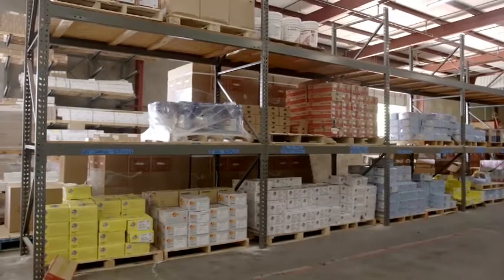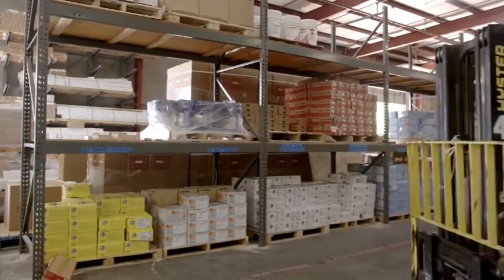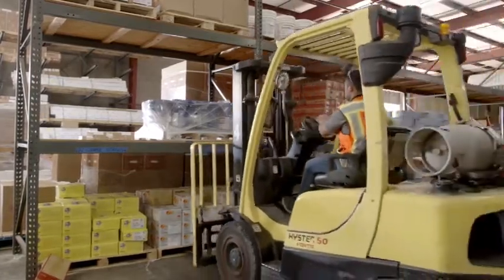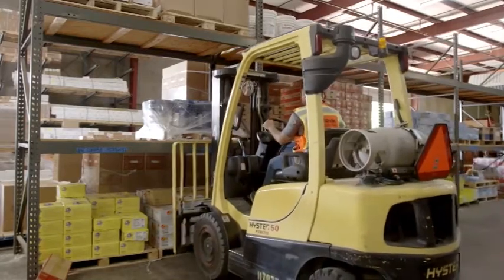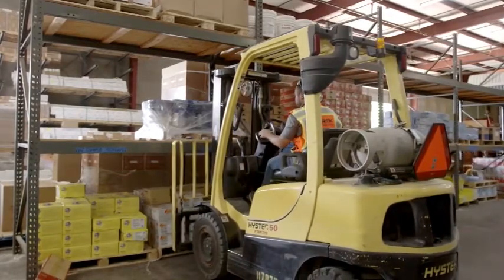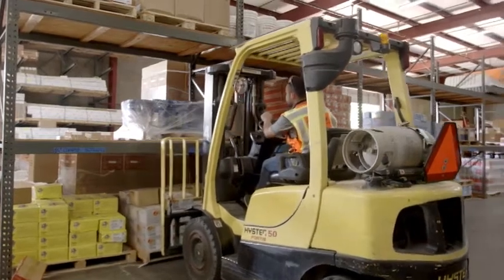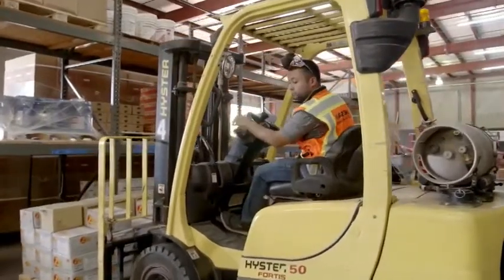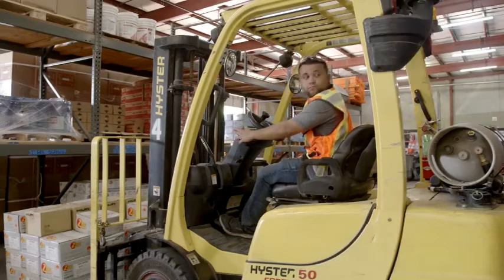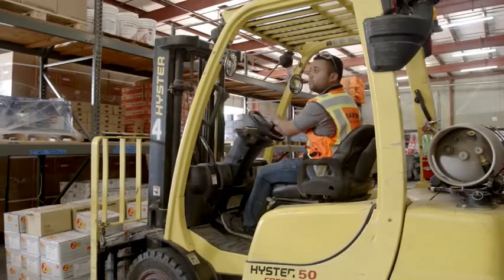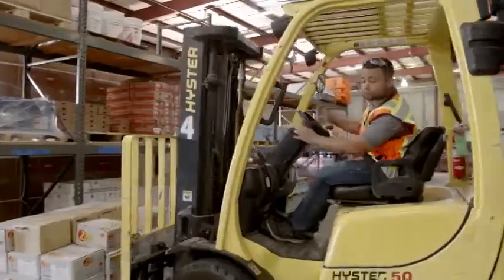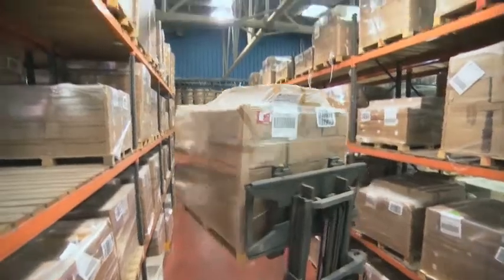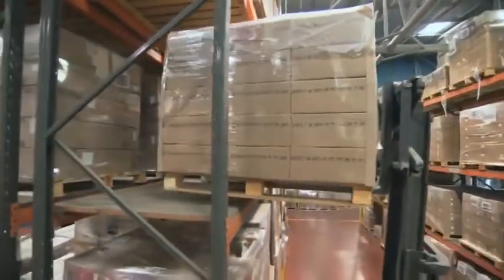Approach the load slowly and carefully, and make sure the truck is squarely in front of the load and the forks are set at the correct height. Forks should be placed under the load as far as possible, at least 2/3 the length of the load, and the mast tilted back carefully to stabilize the load. Carefully lift the load off the ground just enough to clear. Tilt the mast back slightly to rest the load against the backrest extension. When stacking or tiering, tilt backward only enough to stabilize the load. Use extreme caution when tilting loads.